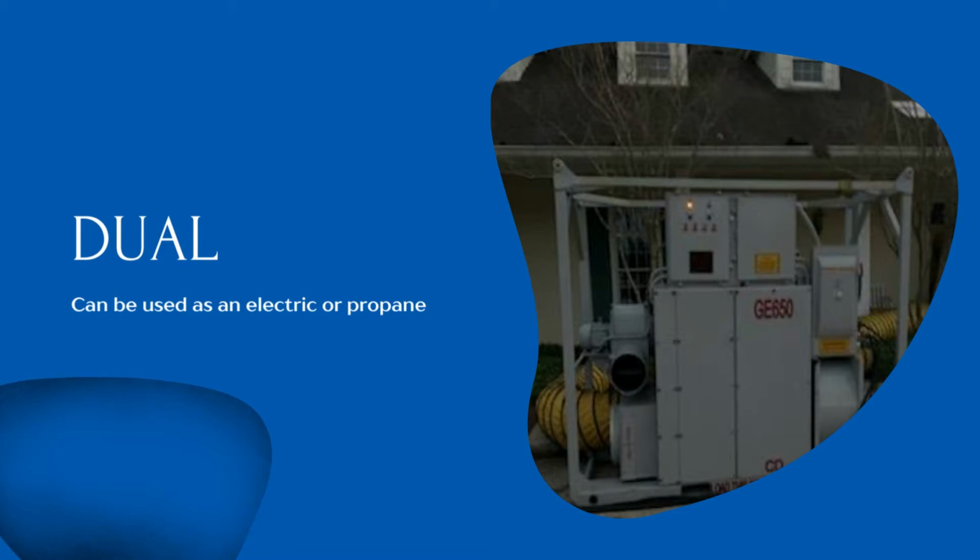Sometimes you want all electric for whatever reason that you have. This is the same unit seen in the other picture. It's dual fired. It'll run on either propane or electricity, either one. If you're on all electricity, you're going to need 150 to 175 kW. If you're running on propane, you can run it on a 45 kW because then your propane is producing the heat for it.